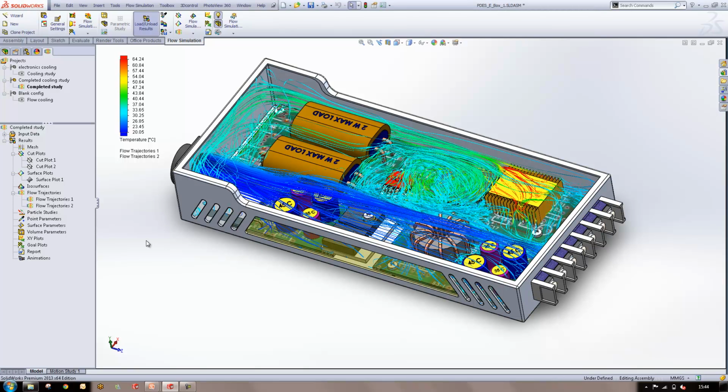Okay, we've got a couple of other tools that we can use that we're probably going to see later on. I'll show you in the valve example instead. But we can inject particles of a mass this time, so we can conduct what's called a particle study and inject, for example, tiny iron particles or fluid like water particles, anything like that, and see how they behave within the flow. Obviously they carry a mass and hence their behavior will be different, their momentum will be different.